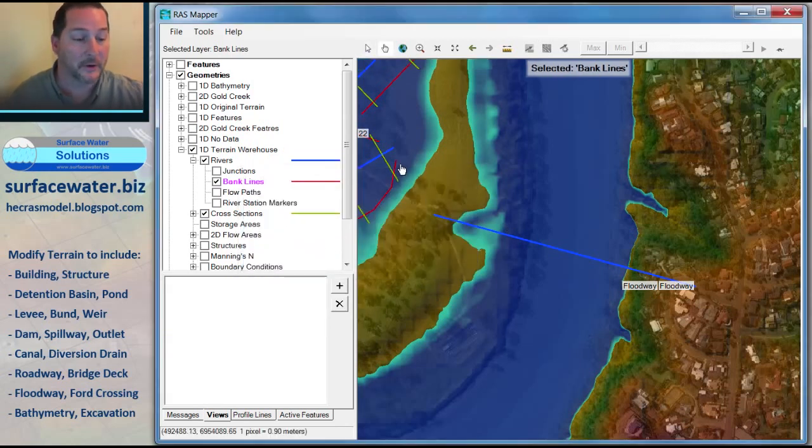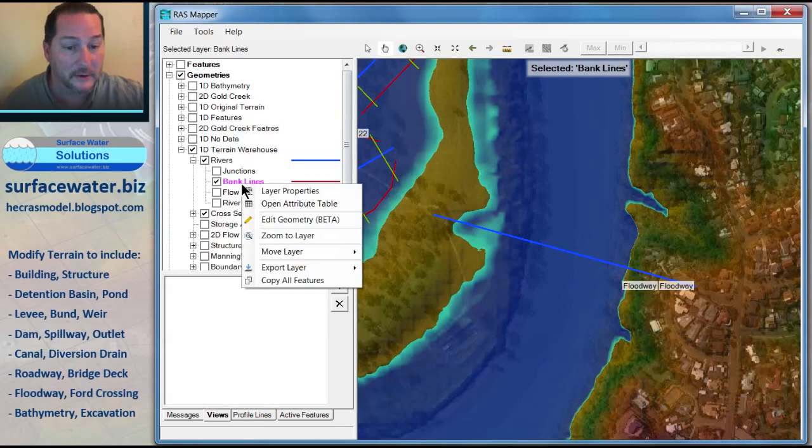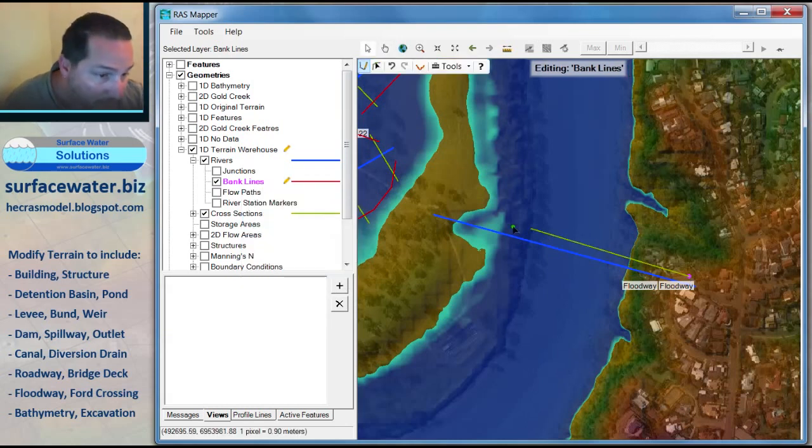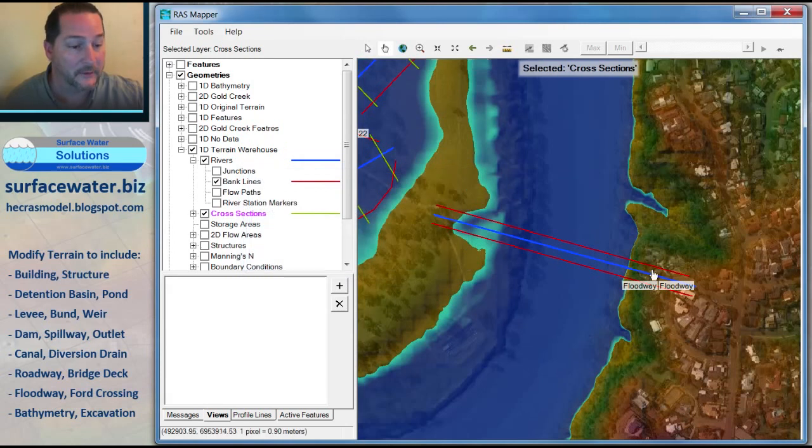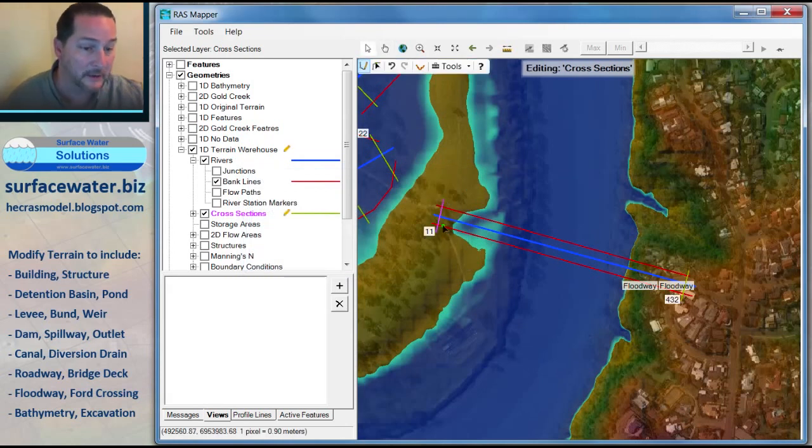Now, if I've got vertical walls on the edge of this, I can just follow right along with this thing. So I'll go here from this end to this end, and again, do it this way with a cross section that's going to just be on the ends here, and interpolate everything in between. And so again, this becomes the extent of my roadway between all of these lines.